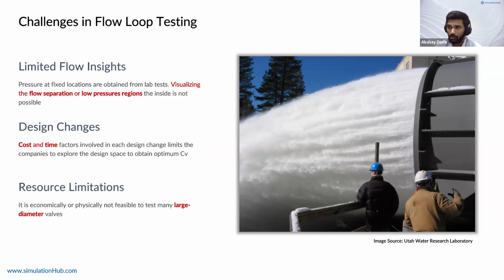There could be a chance that such large designs might not even be possible to test in that testing facility. It could be due to the size itself. Second is, again, transporting such a large valve and getting it back. So all of these add a lot of challenge in physical flow loop testing.